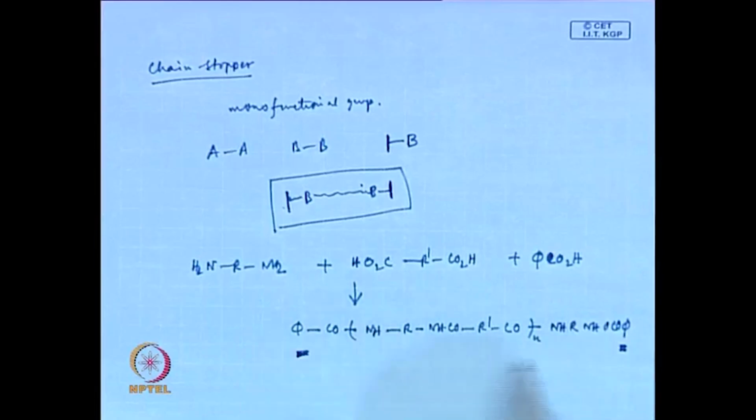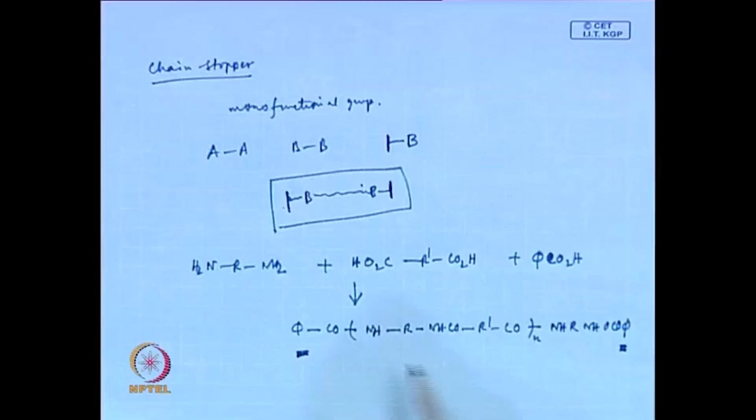So, if you take this polymer out and do further molding and compounding, then because these chains are capped with a non-reactive group, they will not take part in the reaction, which means your polymers are practically dead polymers. So, your molecular weight does not change. At the end of your processing steps, you will get the same polymer with the property related to your target molecular weight.